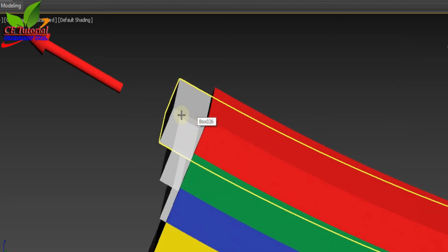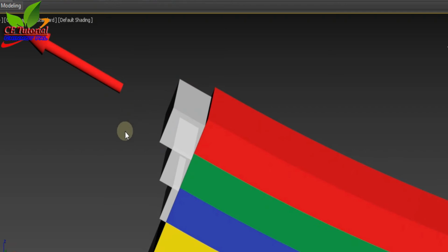You can see the amount of strain here. So the total amount of strain will be 2 multiplied by this distance, because both ends will shorten with the same magnitude. Now you can calculate the strain by the formula, change in length divided by original length.